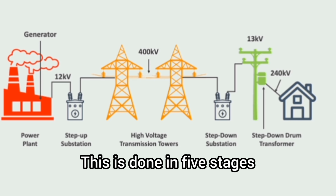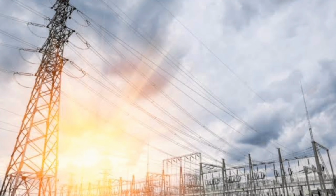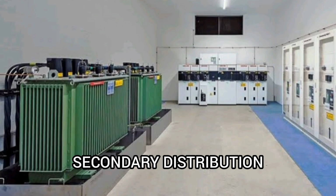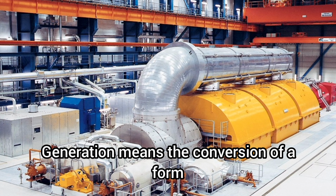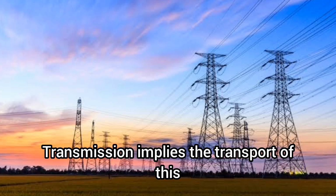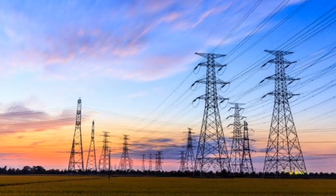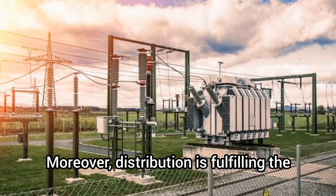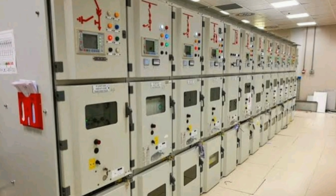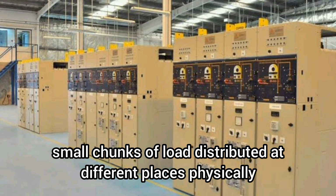This is done in 5 stages, namely, generating station, primary transmission, secondary transmission, primary distribution, secondary distribution. Generation means the conversion of a form of energy into electrical energy. Transmission implies the transport of this energy over very long distances with a very high voltage magnitude. Moreover, distribution is fulfilling the demand of the consumers at certified voltage level, and it is done in terms of feeders. Feeders are the small chunks of load distributed at different places physically.